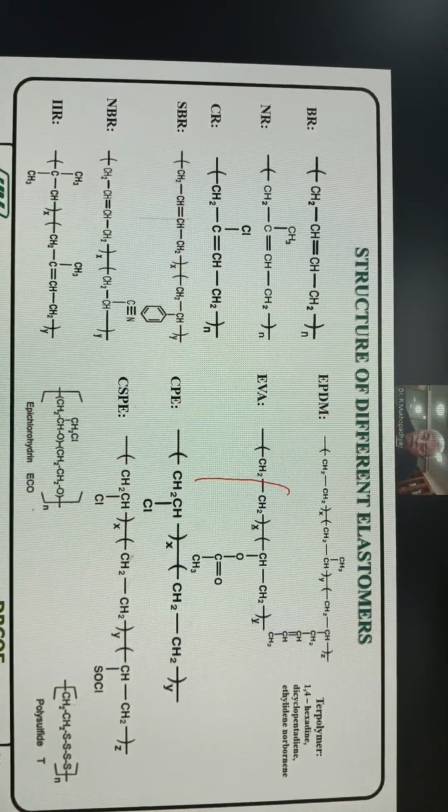And then there are mostly main chain saturated rubbers like EPDM, EVA, chlorinated polyethylene or chlorosulfonated polyethylene; in all these cases the main chain is mostly saturated. All these require different curing agents, mostly peroxide and in some cases special ones. And the cure rate for such polymers depends on the type of unsaturation present, the mole percentage on the side chain.